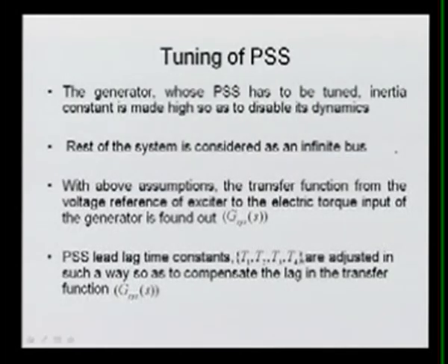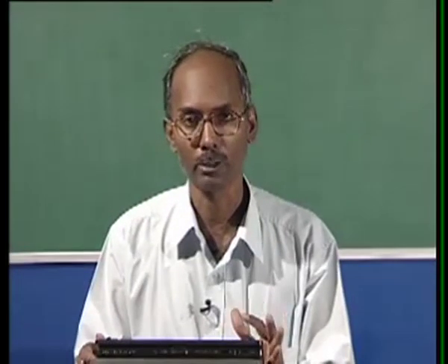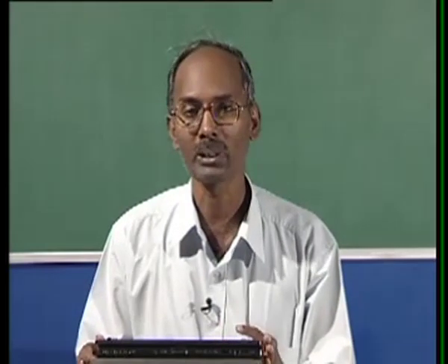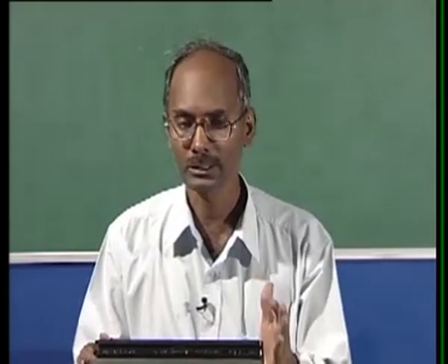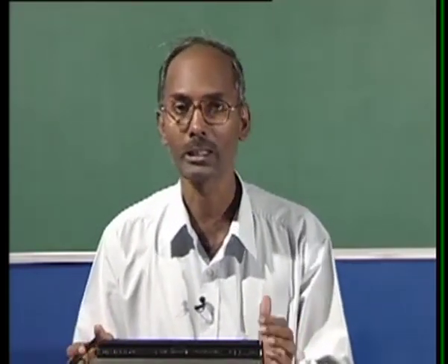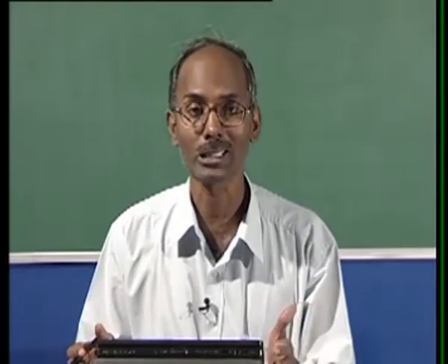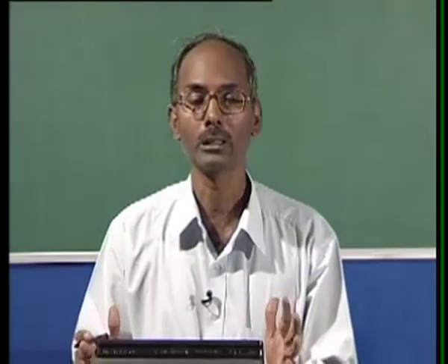So for the tuning of the power system stabilizer, we have to get the various parameters. The gain is very important. If your gain is not tuned properly, your system will be unstable. The tuning of this gain is very important, and it depends upon the system operating condition. We know very well that system conditions keep on changing: the load keeps on changing, and the generation is also changing. So your system in terms of power is also changing.